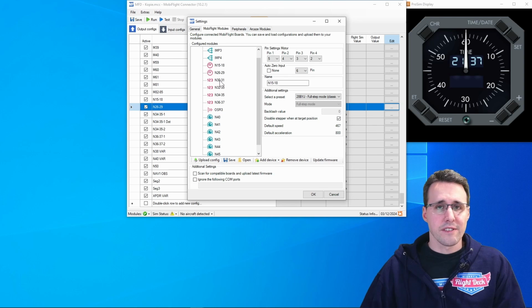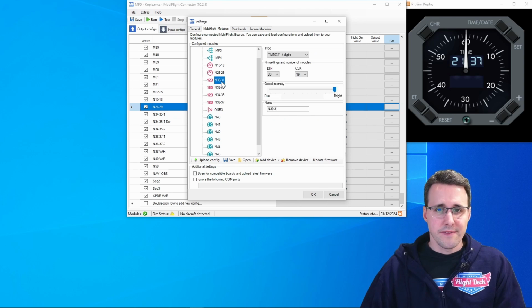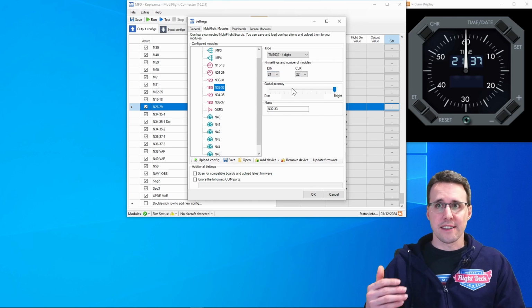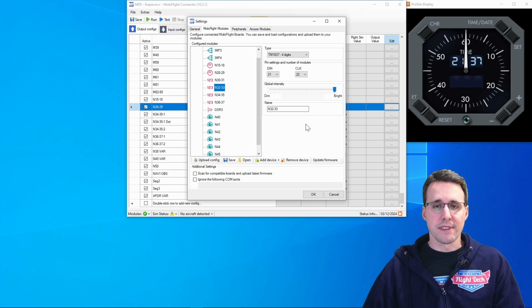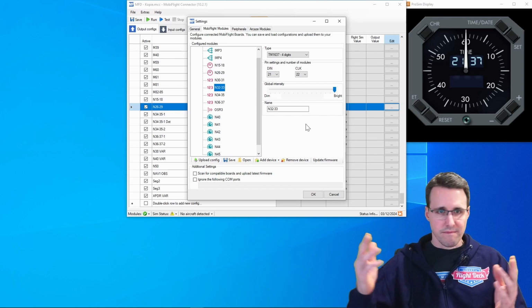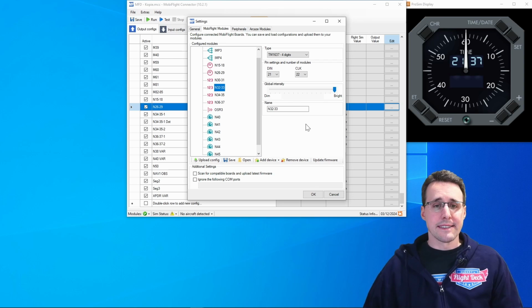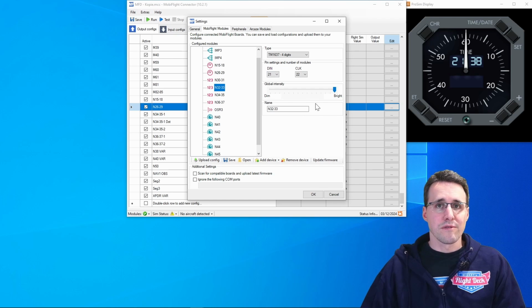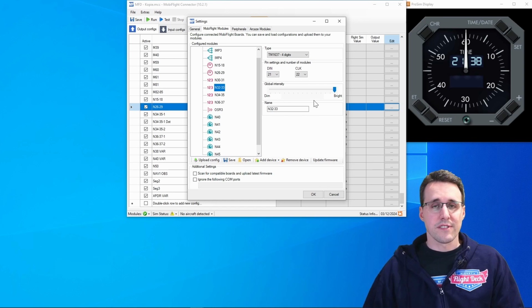And here are the two display drivers: this driver here for the upper 4 digits and this one for the lower 4 digits. Remember, you can't cascade these drivers like the Max chips, for example, where you can cascade up to, I think, 4 or more in a row. In this case, for the TM1637 driver, you have to connect each of the drivers directly and separately to your Arduino.